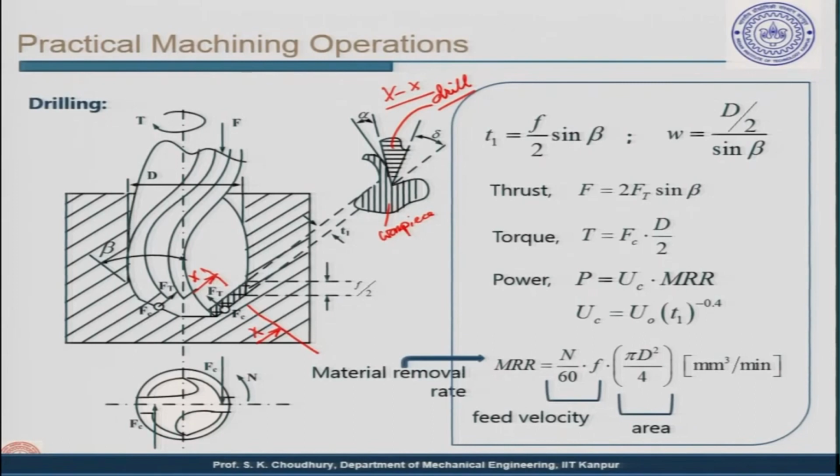All right. Now, the forces are very different. First of all, once again the torque, that is the rotation of the drill, and the thrust by which the drill penetrates, and that is equivalent to the feed. Without the F, the tool could not have been fed to the workpiece. So, this thrust force which is imparted to the drill feeds the drill to the workpiece.